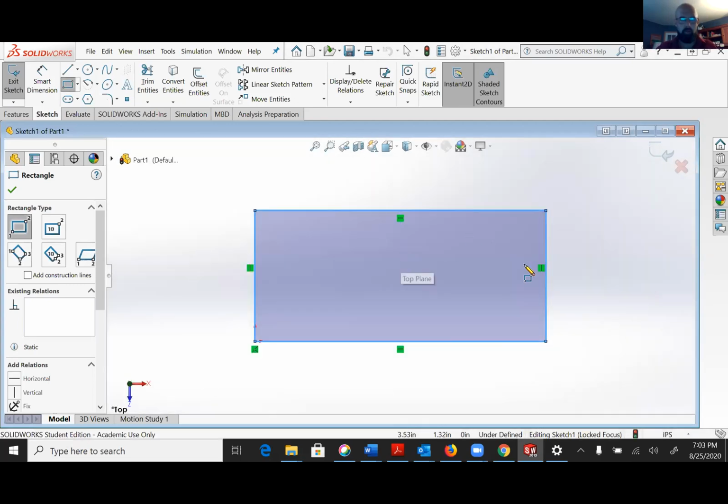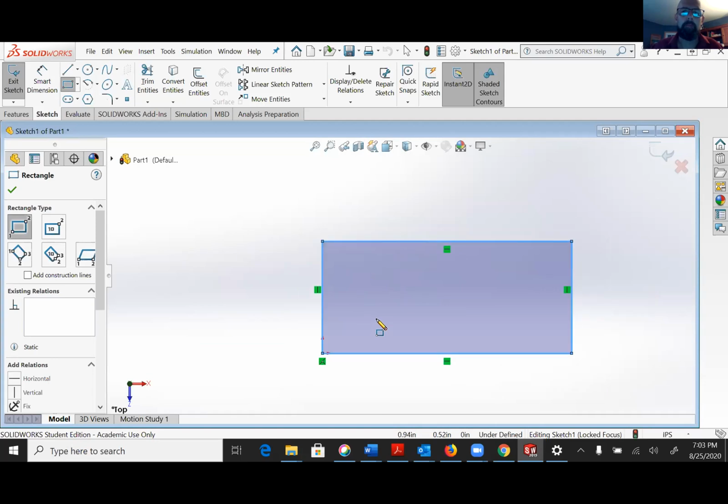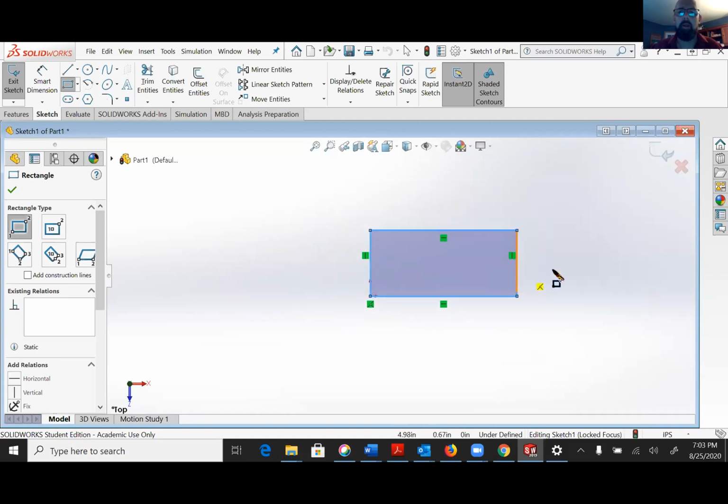What I haven't shown you also, and I'm going to let you guys that have it open play with this real quick, is the mouse. I'm rolling the mouse wheel to zoom in and out. I hold the center button down. Notice how that rotates around that axis point.